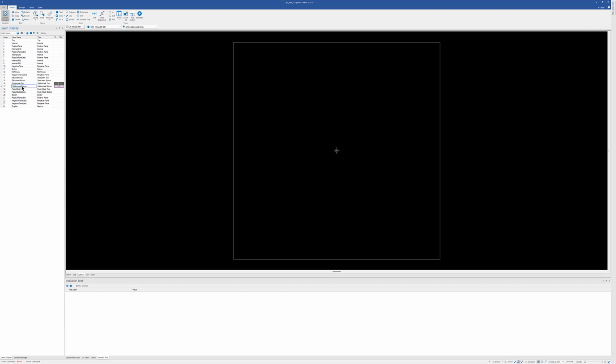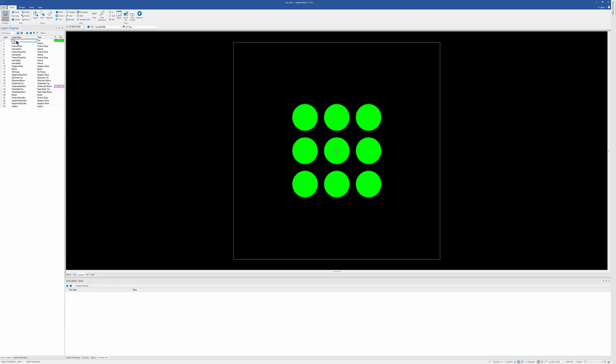We don't have solder mask clearances, so I would probably go ahead and add them at this point and then just resave the symbol. But for our purposes, we've created the symbol. Now we've got our two symbols in here. This one that we created with the draw to symbol, and then we have our square fiducial that we created manually. So one last time, let's go in and create a panel, and I'll show you how you use the symbols in the panel.